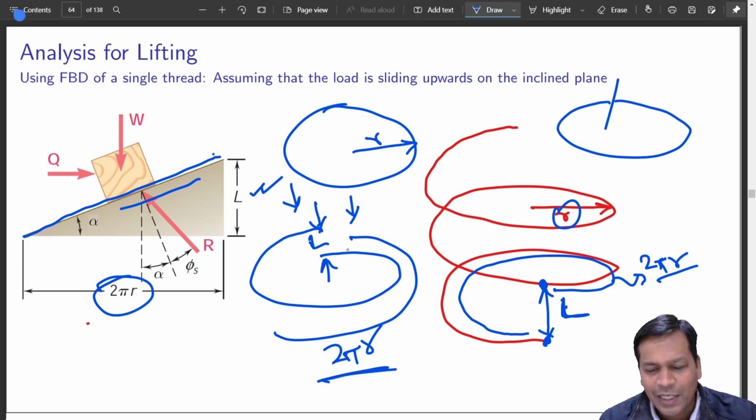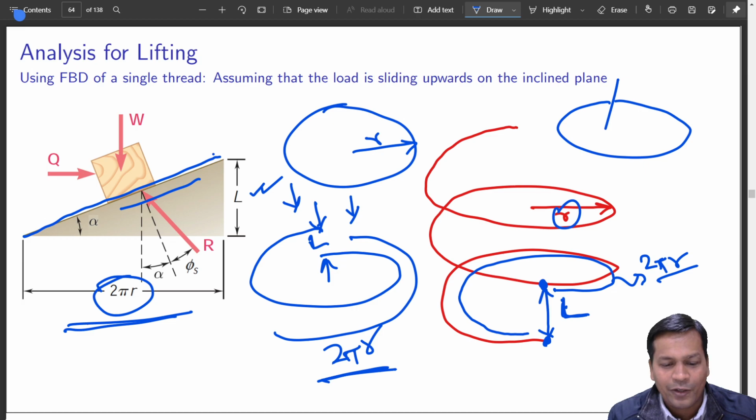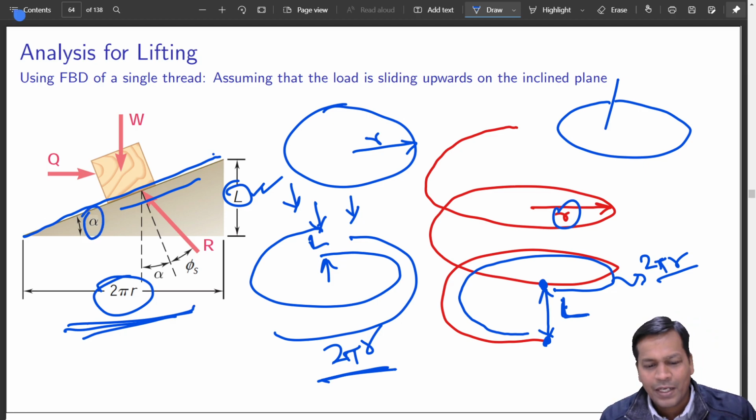So giving an example of a bangle just to make you understand, that doesn't mean that 2 pi remains there. Actually, if you look at that broken bangle from the top, the mean radius of that is r, and that circle is of 2 pi r. That means that projection is 2 pi r, not this inclined one. Okay. So this is the vertical lift, this is the horizontal distance, this is the helix angle. So it is all opened up figure now.